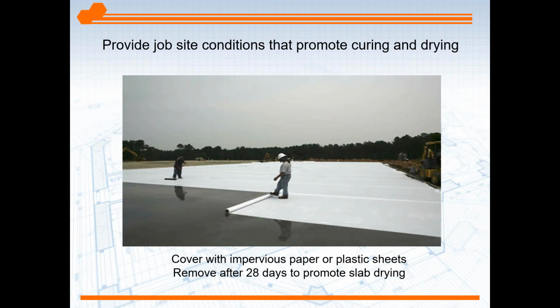Once the concrete is placed, we want to retain moisture in the slab for at least 28 days. We need moisture to promote concrete curing, cement hydration, strength gain, etc. This is a very effective means, putting down a sheet, pervious paper or plastic. The challenge here, especially with this very large installation, is keeping that sheet down where the wind doesn't blow it off, etc. But once that concrete is cured at 28 days, you need to remove it to allow drying to start. As long as that sheet sits on the surface, drying is inhibited or greatly delayed.